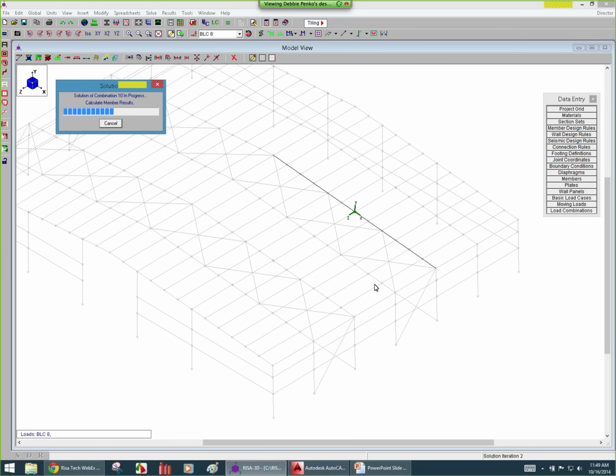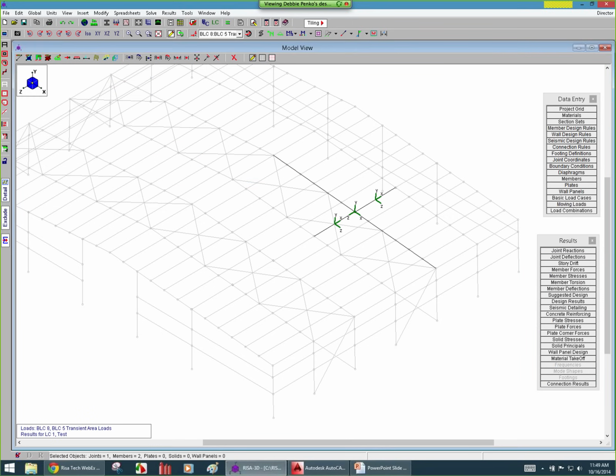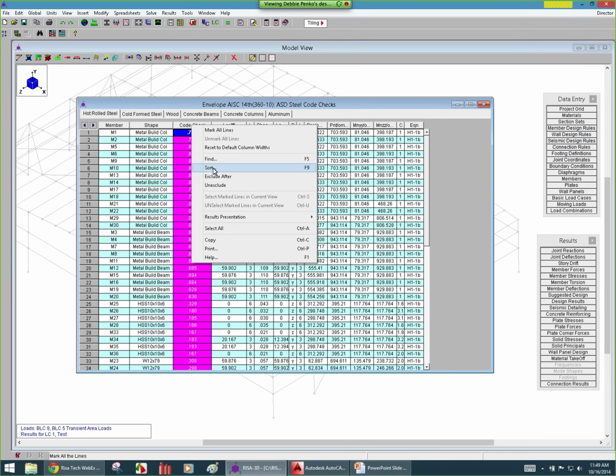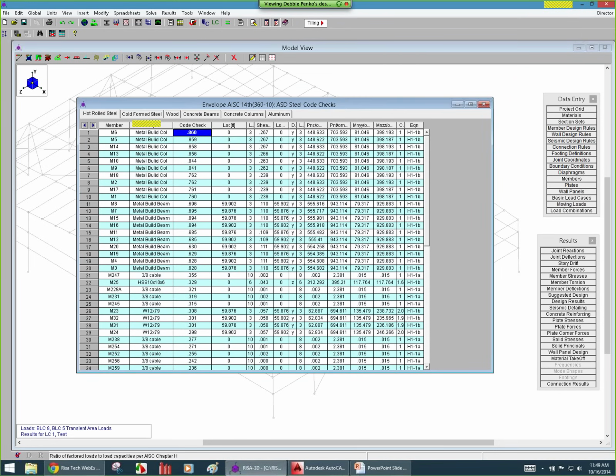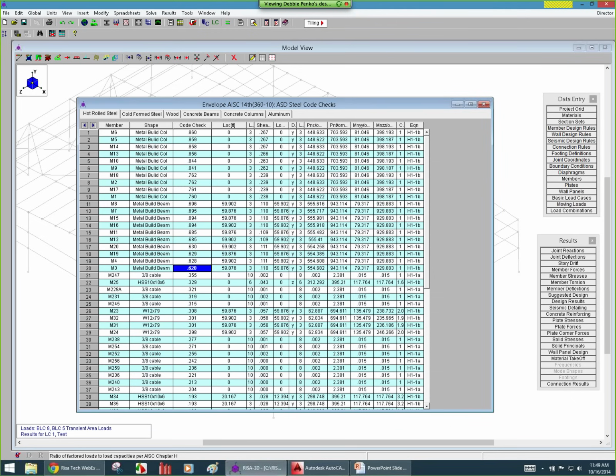Now, it is important to also make those considerations. Sometimes things aren't bracing, even though you might say, hey, I have something framing into it, it's bracing. But what if it's a very large member and you're not going to consider it a brace point? So that is something to consider too. You have to be realistic of what can brace what. So all of a sudden, things look a lot better. So it's kind of a false positive there when you start looking at design results and you haven't even thought about unbraced lengths. So those seem to be really good.